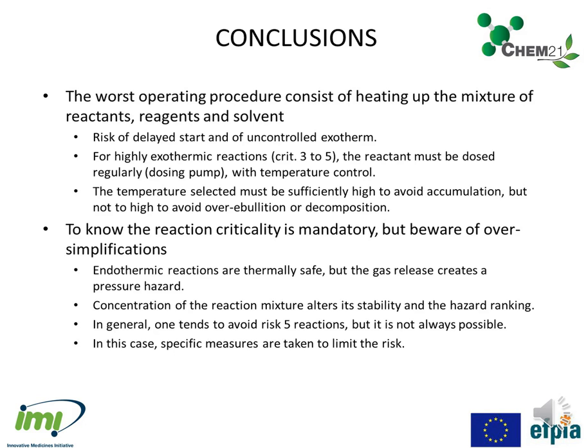It is mandatory to know the reaction criticality, but beware of oversimplifications. Endothermic reactions are of course thermally safe, but if the gas release is important, an overpressure hazard is generated. Concentration of the reaction mixture alters its stability and may change the hazard ranking. In general, we try to avoid the scale-up of reactions ranked 5, but it is not always possible. In such cases, specific measures are taken to limit the risk.